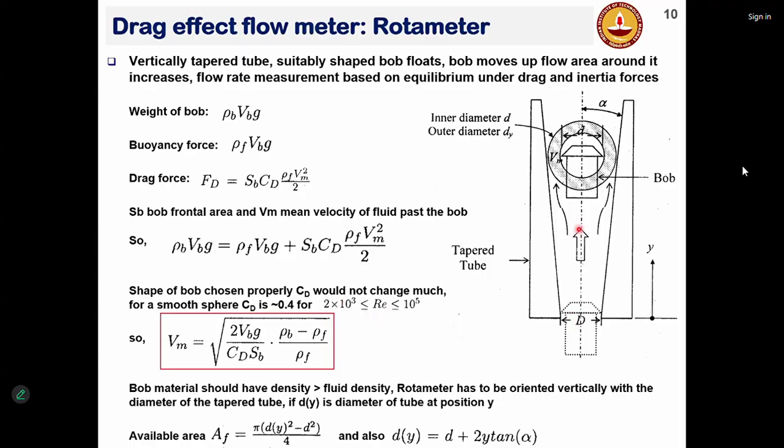Because if the flow rate changes and every time you have to know what the discharge coefficient is, that itself brings in uncertainty, because there will be a change in the flow rate effect on the CD. That means you are measuring flow rate, but then your CD is a function of flow rate. So it becomes implicit. So to make sure that CD is minimum.